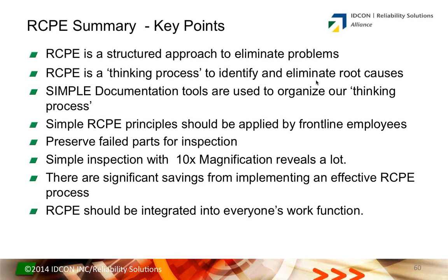Simple RCP principles should be applied by your frontline employees. Start preserving parts for inspection. I can't count the number of times where I've been asked to go to a site to assist in problems, and I go find evidence by dumpster diving. Now, it's good fun, dumpster diving. You pick out all kinds of good broken parts in there, but it's a lot better if people are preserving the evidence up front. Get lay-down tables where these things can be put down.